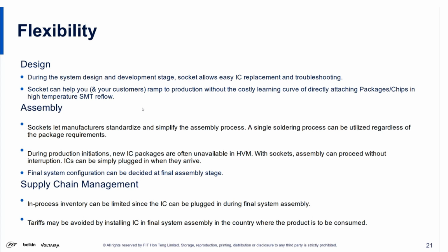So let's talk about some of the advantages of sockets. From a design standpoint, it allows some flexibility. During the system design and development stage, sockets allow easy IC replacement and troubleshooting. So rather than having to desolder a chip from your board, you can do system level testing during the design phase of systems, rather than having to SMT the chip directly to the board. You can do system level testing without having to worry about the chip being permanently attached to the board.